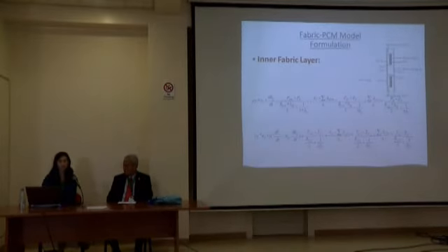Now, starting with the inner fabric, the first equation is the mass equation. The regain of the fabric, which is RIF, will be calculated at each time step. The regain means the mass of water vapor per the mass of the dry fabric. And the change of the regain will depend on the vapor pressure difference between the inner fabric and the surrounding medium.